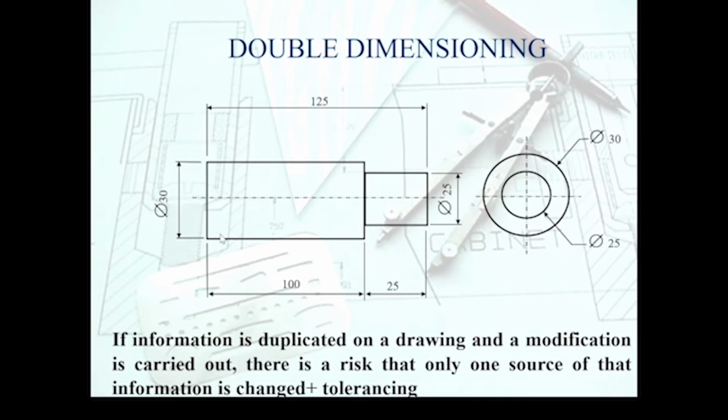Only because a CAD package can dimension anything you would like to click on, that doesn't mean we should be dimensioning all the random details. You know, they need to be sensible, and the drawing has to be neat with an optimum amount of information, also complete. So in this case, definitely let go of this 25 here, that 30 and that 25, to make it into a nicer, more acceptable drawing.